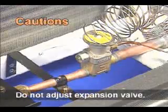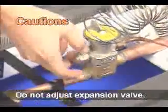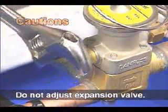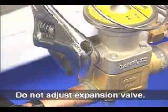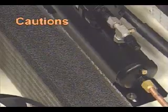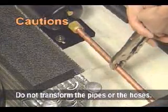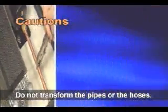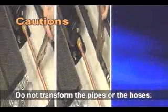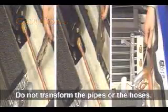Do not adjust the expansion valve. In particular, it is wrong to adjust the expansion valve because of poor cooling performance. We should find the correct cause for that. Do not transform the pipes or the hoses. Transformed pipes can cause poor cooling performance due to the resistance of refrigerant flow and may result in a crack after all.